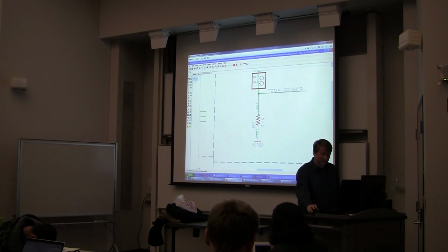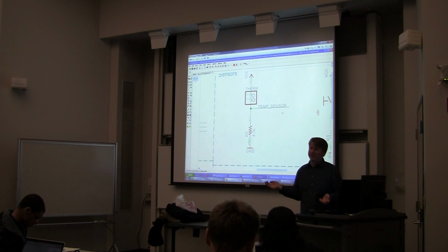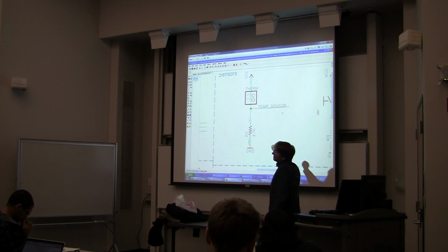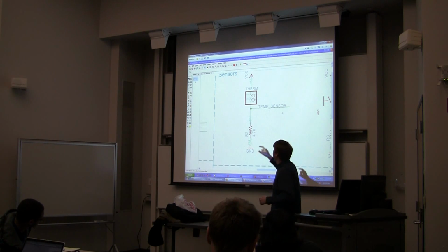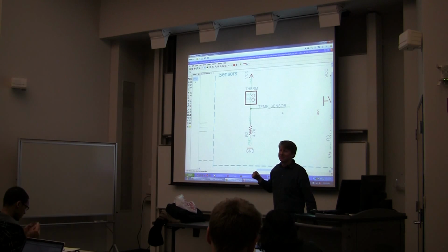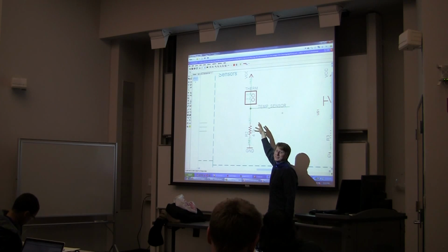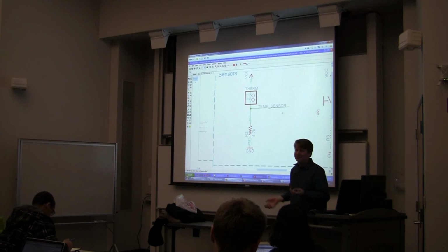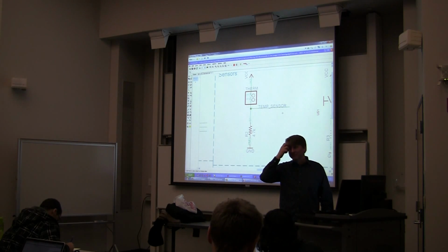What you can play with is basically, with this voltage divider, you buy a thermistor which has a variable resistance, and then you see how much dynamic range you have. If we got a 100 kilo ohm thermistor, this would not work very well because the value of that 100 k ohm resistor would change a lot, but the ratio between the two would not change a lot. So what we usually do is we take 4.7K here, and then we use about a 4.7K to 10K one there, and then we end up getting a reasonable resolution, maybe 6 bits. So you say, well, I can probably tell temperature to a degree or so, which without fancy calibration is probably good enough. Yep. When you use a thermistor, do you have to calibrate it yourself?